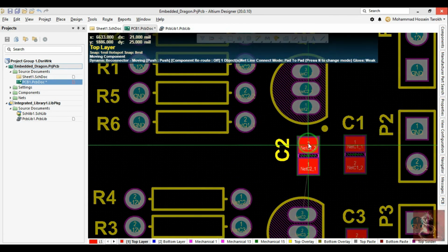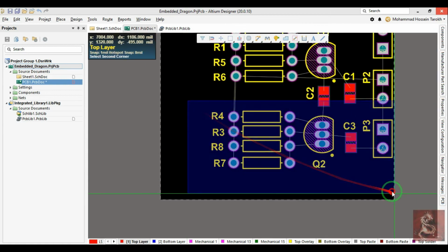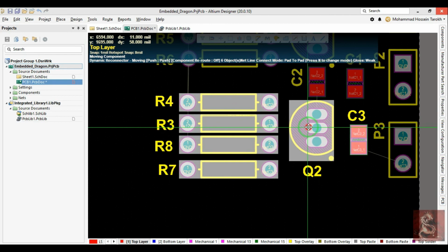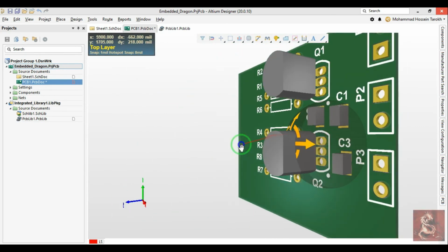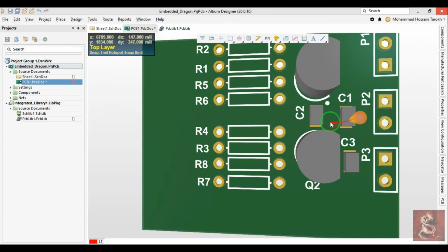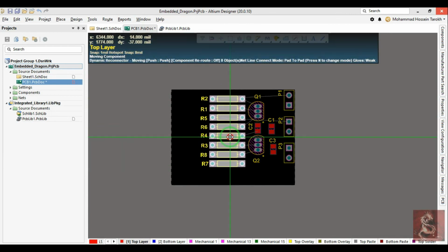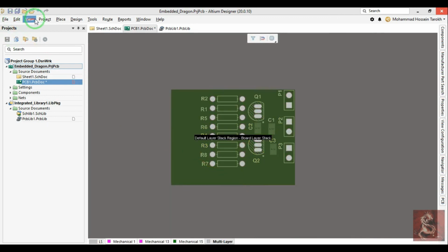We don't need a lot of space in this case. So if I move this a little here again, and also move the components up again, we have distance, because at the end this transistor has a height, and you first solder these assembly components. In reality this is not a problem. Now we can also distribute them equally like this to make the board even more beautiful, and we still can make the PCB smaller.